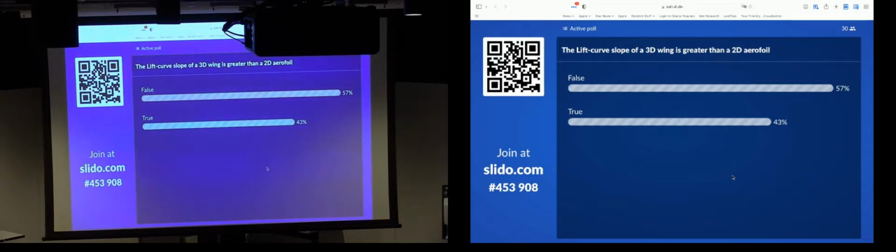And they have a wall at each end. And they are 2D, or effectively 2D. They behave like 2D airfoils. Now, they are directly in the wake of the preceding blade and all of that stuff, so it's much more complex. But we don't have any of those things like tip losses and things like that.